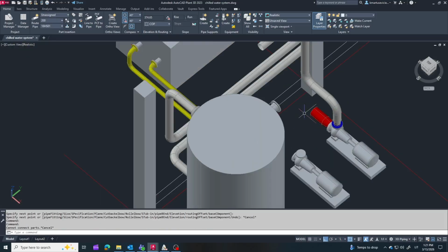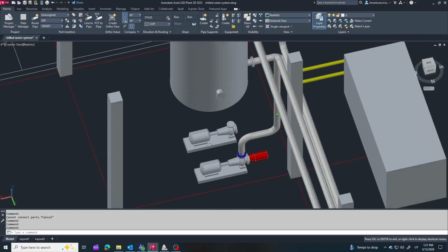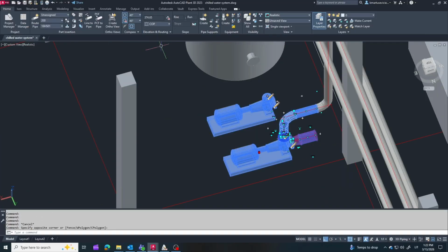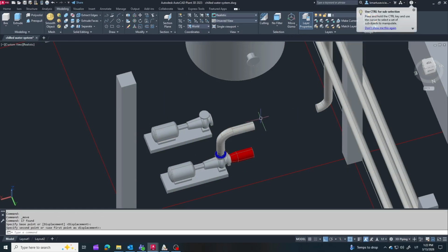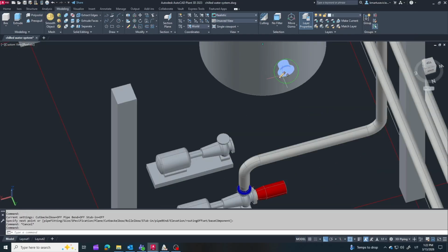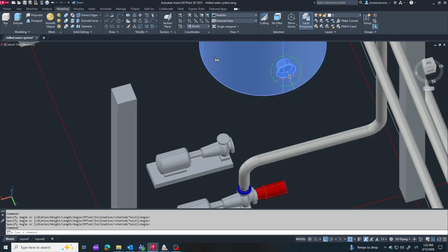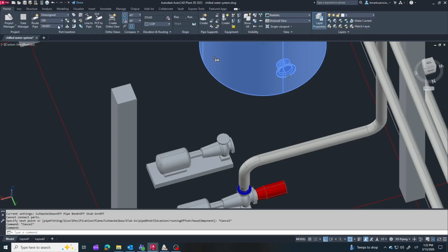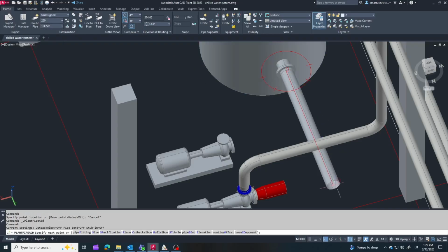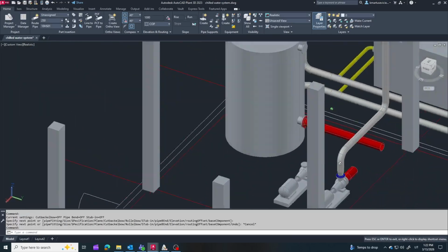In this layout, the pumps take water directly from the buffer tank. The tank acts as a stable water source, so the pumps always have a consistent supply of water, which helps maintain reliable operation. The buffer tank also helps separate the chiller loop from the user loop hydraulically. This means the flow rate in the chillers does not have to be exactly the same as the flow rate in the user loop, which makes system operation more flexible.